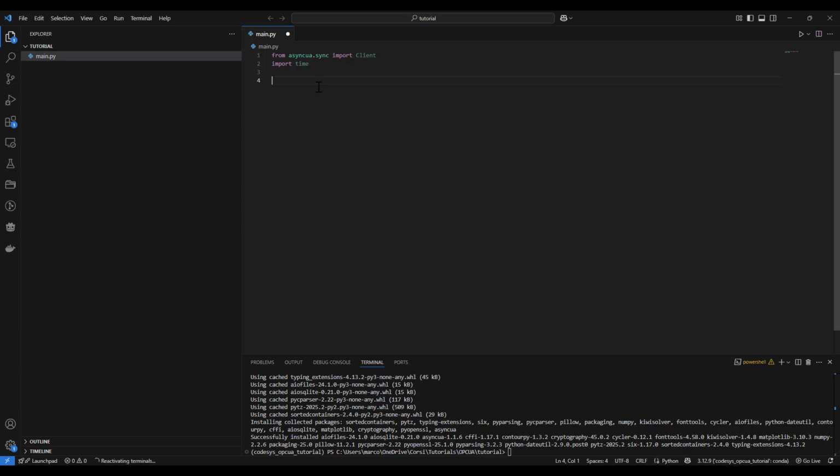And right now I would need two things to create the client for the OPC UA server. I will need the OPC UA Server URL that will be a string, and also we will start from an example to read just the axis position from our OPC UA server. So I will need the node ID of the variable.